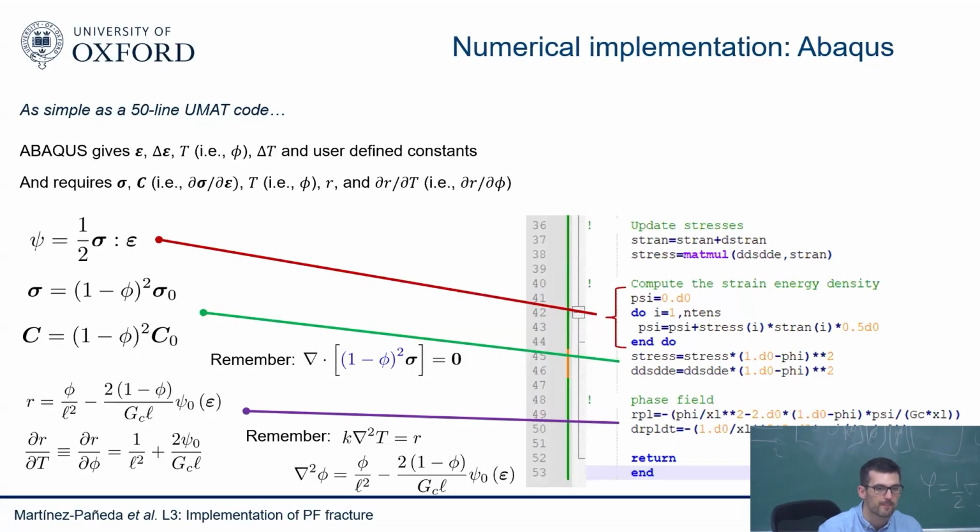Yeah. So earlier we spoke about this splitting, right? Strain energy splitting. So if I implement it in UMAT, how do I take it? That's a good question. We do have the codes for that. Basically, what we do is replace this very simple expression with our own subroutine where we say, okay, you add a flag variable and you tell me you want to do volumetric deviatoric, spectral, no tension, whatever you want, and then you calculate this C quantity in a different way. It's a different expression. It's just changing that equation. But we do provide a code, what we call the generalized code, which has not only AT1, AT2, and phase field coefficient models, but also different splits for each of those models.